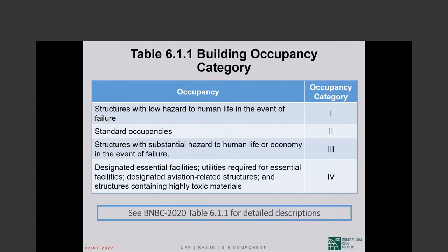So back in those days, the zone in which a structure was located determined the height limits for a structural system, like bearing wall systems could not be taller than 160 feet in seismic zone 4. The zone determined the level of analysis you had to do as the basis of design.